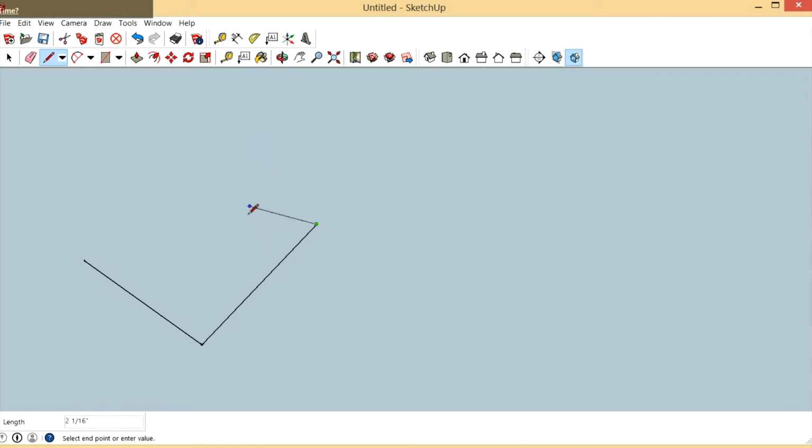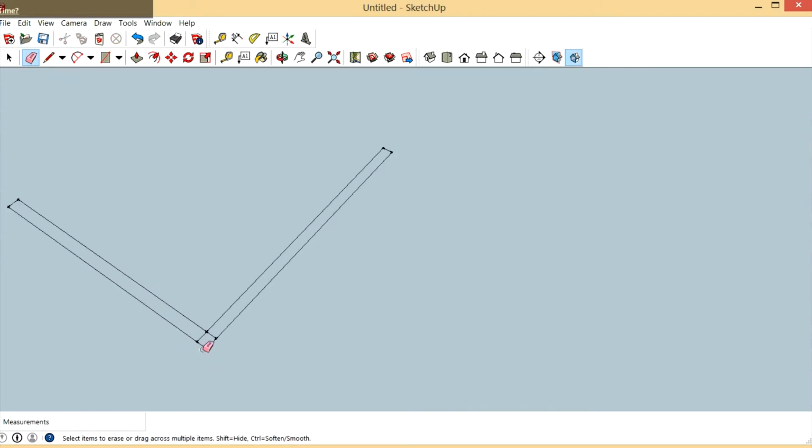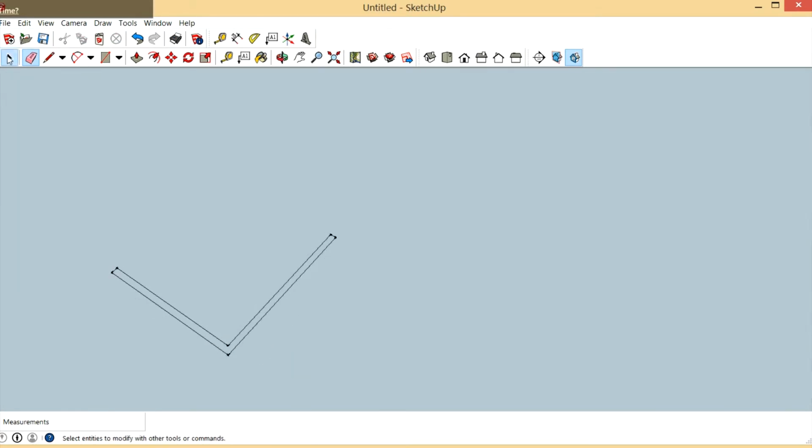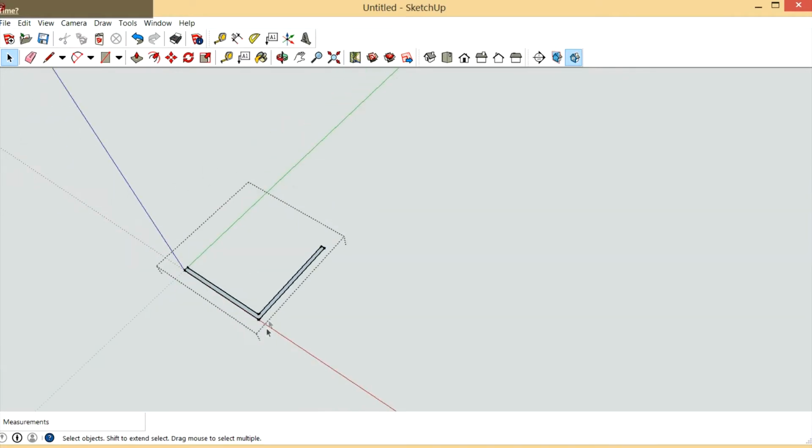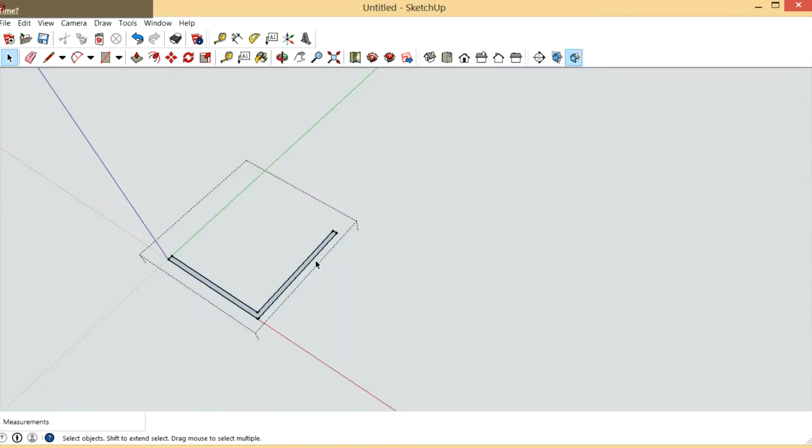And it's going to have a thickness. It's not going to be 1/16 of an inch thick, okay? But I'm going to draw it 1/16 of an inch thick so you can see what we're doing here, and it just helps to give it a little thickness. When you're drawing details, it's easier to see if something has thickness. So what I'm going to do now is just grab that and make a group. Okay, now I can work with it. If I double click on it, I don't have to worry about all this other stuff around it.